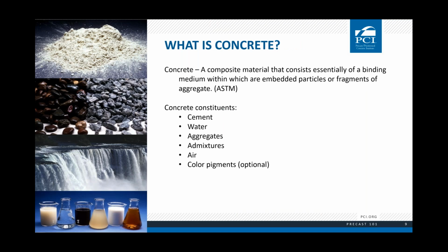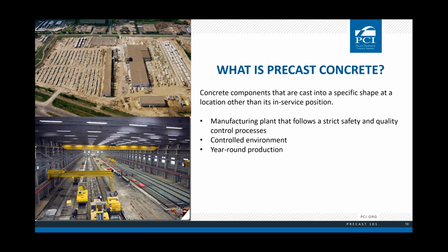I think we all are familiar with concrete, but what I want to point out is that concrete used in precast applications is a high early strength concrete, and it also includes additives to accelerate the curing process, resist the effects of freeze-thaw, and it can reach high compressive strength, especially in structural components with long span members.